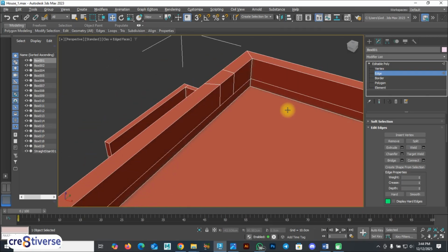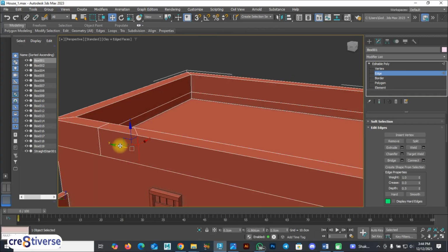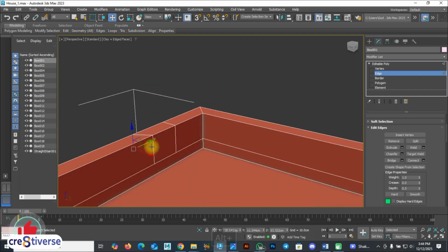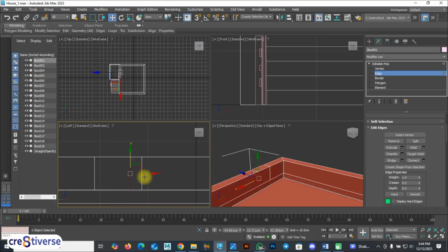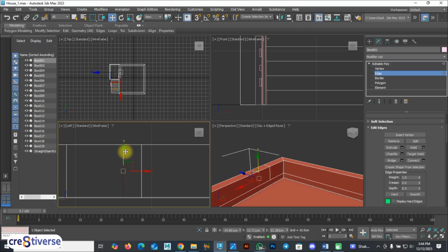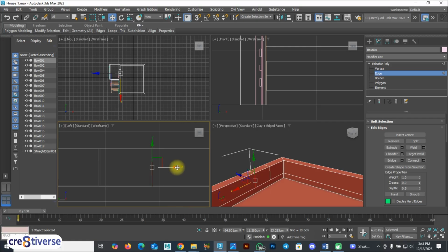So to correct this, all I need to do is, if you click this now and you look at your value of y, I could just click this, go to my orthographic view. Okay, see the one in front here, see the one behind, which is this here. So I could just move it to be in same line with the one at the back. That is the importance of the orthographic view and viewing in wireframe mode. So you can vet if things are lined up the same way or in the same line. You can see, look at it updating here. So I could just move this.